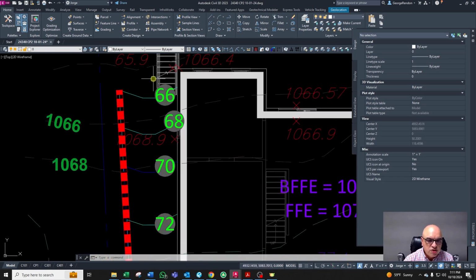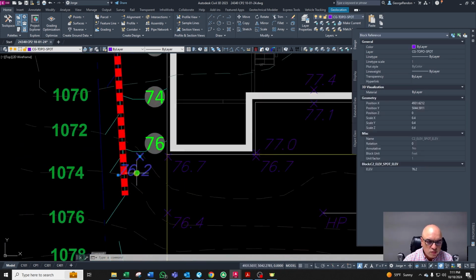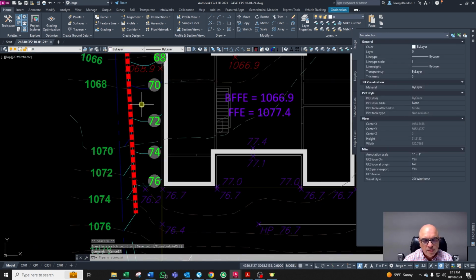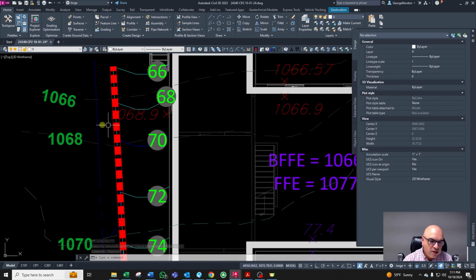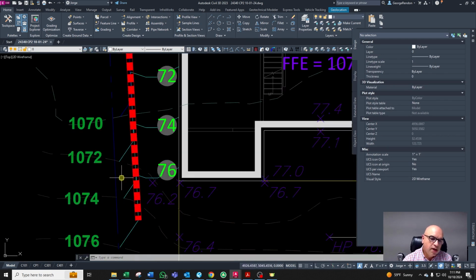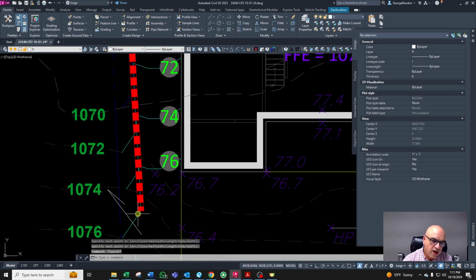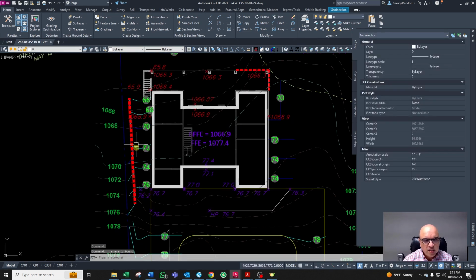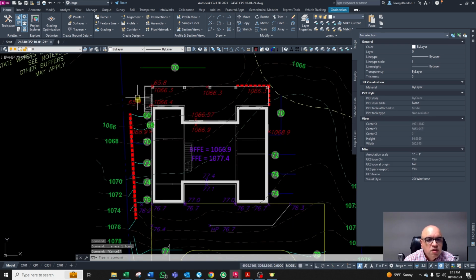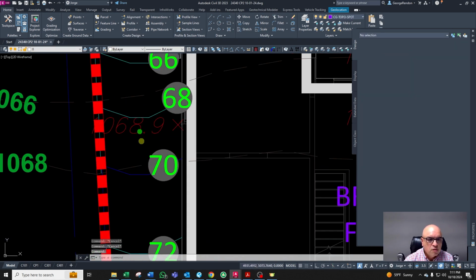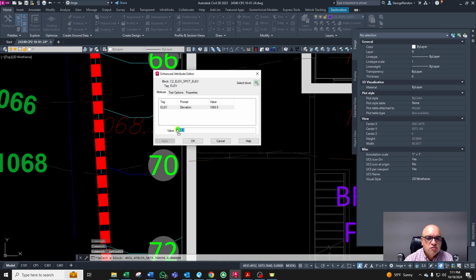So we still have the swale that is picking all this water, and we're creating a swale, and we're taking all the water away from the house and away from the retaining wall. And this water actually is going away from us too. So we're forcing this water to go away from the retaining wall that we are proposing. Okay, so we have finished tidying up these contours to the existing ones, because remember, a constraint is an existing retaining wall.